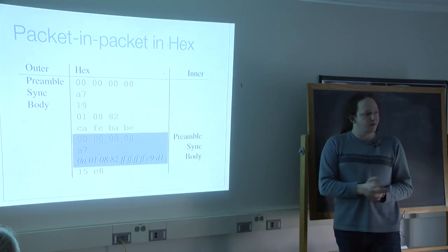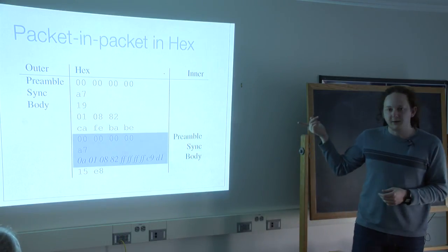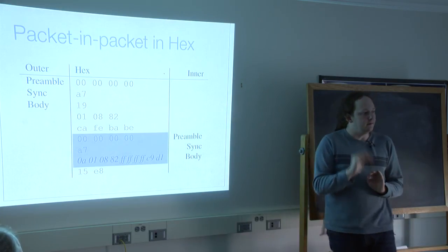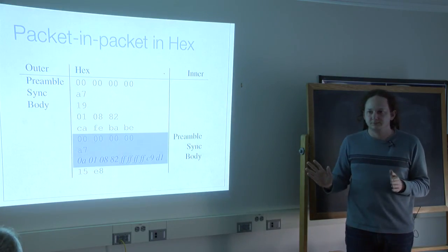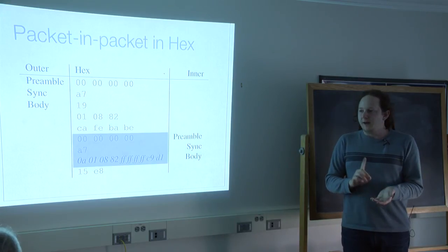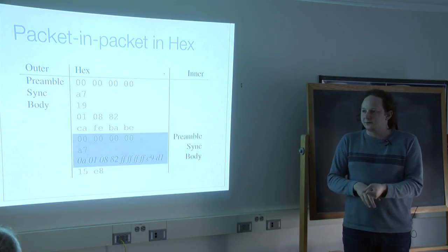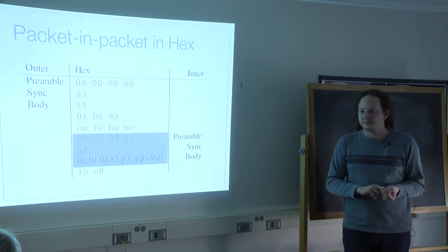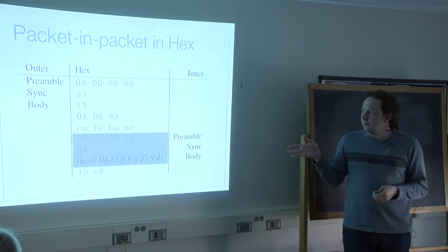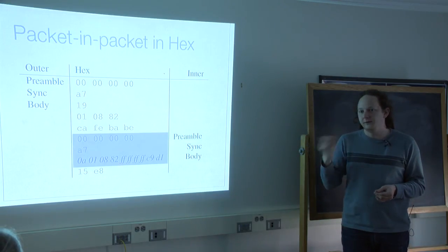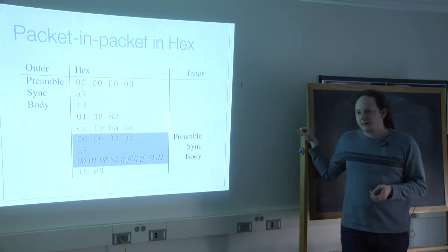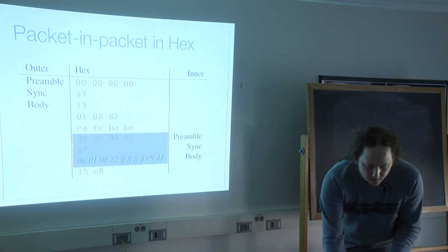with each other. For a short packet, like a Zigbee packet, like 802.15.4, the way that a collision will work is that either your packet is completely obliterated, which is of no use to us, or the end is damaged, which is of no use to us, or the beginning is damaged, which is the exact case that we're looking for. And we've measured in busy Wi-Fi environments that we can get up to 1 out of every 20 packets injected successfully.